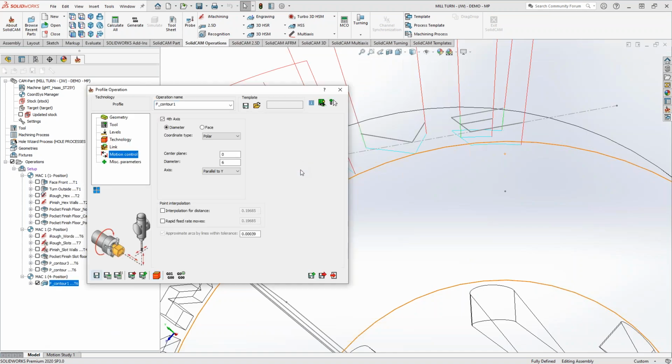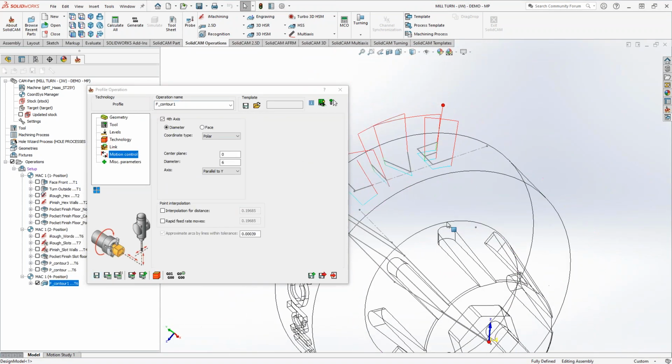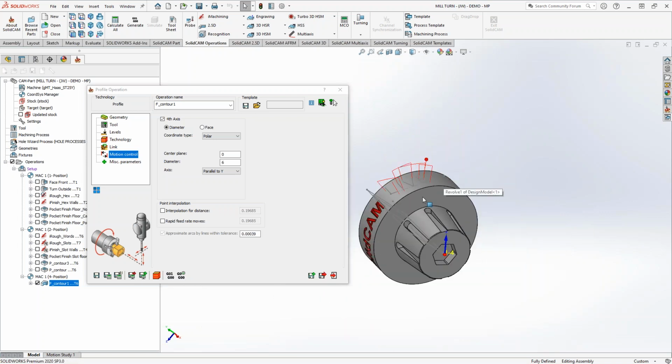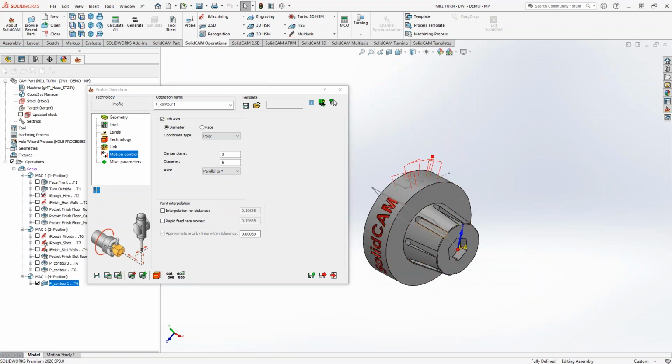A lot of times customers are going through and trying to do some sort of simultaneous fourth axis. They're trying to use the really high level toolpaths. But if you find that you're doing a feature on your part that is cylindrical, meaning that it has a consistent radius all the way through, a pocket or a slot or anything like that, sometimes the wrap geometry is very easy to do compared to the 5-axis stuff. Because to do the same pocketing, I would have to choose the chain, choose the surface, make sure the surface is not, in this case, going all the way around. You know, tool orientations. 5-axis can be a lot more complex, and I usually save that for really complex stuff.